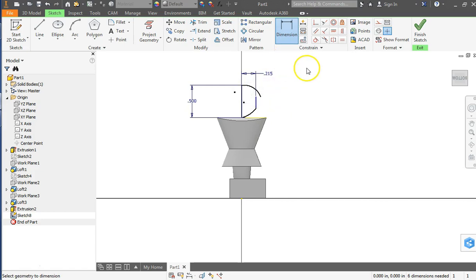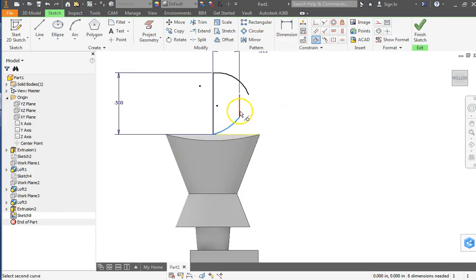All right, and then the arc tools, what I was thinking is I was going to make this arc be tangent here. So it might not even work so great. And let's see, I'll make this tangent to that line. Here, we'll see. And then my arc and line didn't connect here, so I'm going to use the coincident constraint to connect that point to here. Okay, and I'm going to use the tangent tool to smooth this out from here to here.